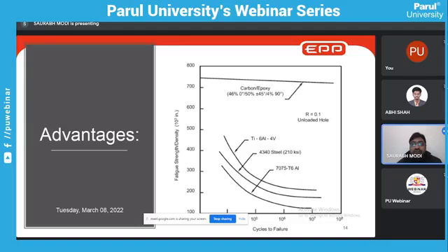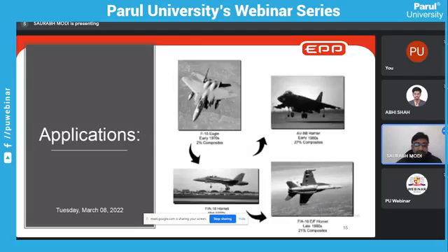So what I want to convey is that you can check the top line. This FRP or GRP composite material is much better in fatigue as well. You can check the line. The steel line is starting at 400, and it's gradually going down, whereas here it is starting between 750 to 700. So you can assume the higher mechanical properties.